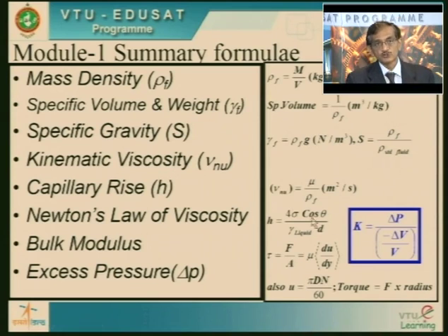Yesterday, remember, we showed you the video also on the same, but mind it well, cos theta, where theta is the angle of contact, is normally almost 0 for water and air, or around 10 degrees, and it may be given in the numerical. If it is mercury, the theta value is 128 degrees or 134 degrees, which gives a negative cosine value. So, capillary rise for water will be positive, and for mercury, because cos of 90 plus theta is minus sin theta, there will be a mercury drop, correct.